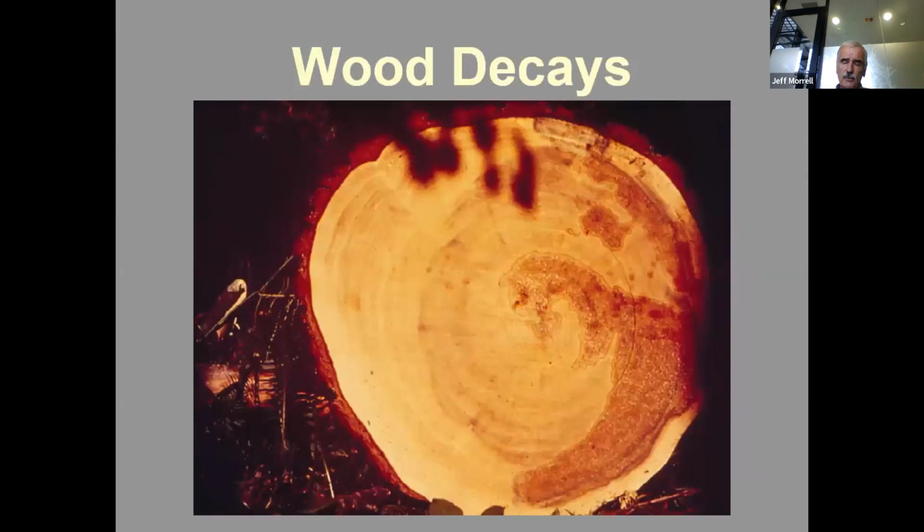As we get into dealing with timber, one of the things everybody sort of knows is, well, wood decays. And when we use wood, we have to understand that. And that process starts right from the start when the tree is live and growing. This particular tree has a heart rot on the right-hand side that has started while the tree was alive. It would actually stop once the tree is cut, but other organisms will get in.